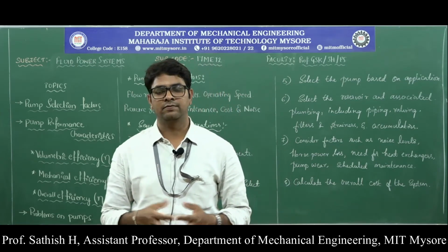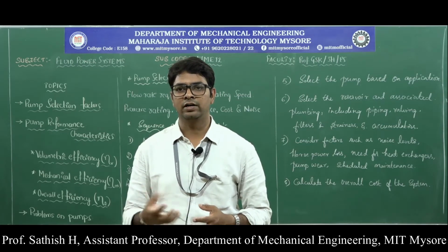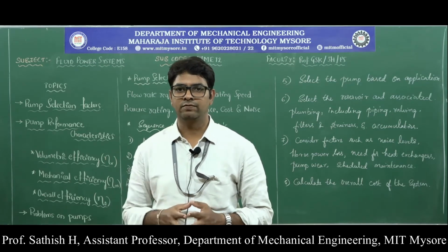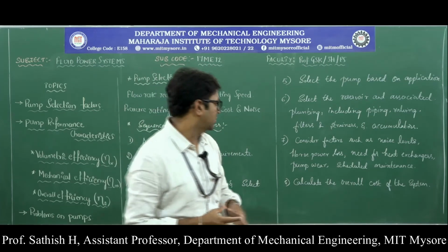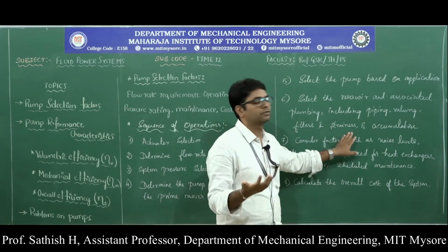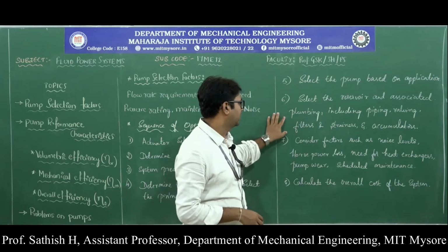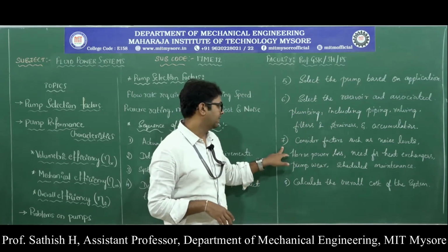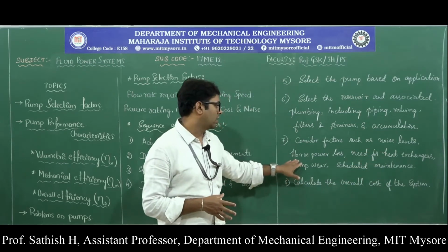Filters and strainers remove any solid contaminants present in the oil before they harm or have an effect on other components of a hydraulic system, for example a pump, the valves, or the actuators. So we have to select what type of filters and strainers we are using in the next step. And then the accumulators. These are the various components you are going to select in step 6. And then the next one, the 7th, is to consider factors such as noise levels,